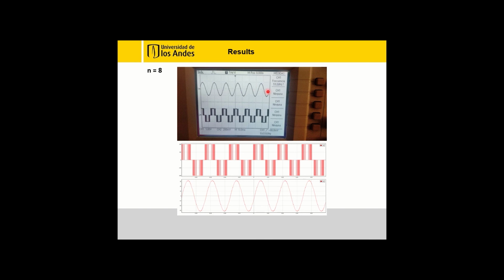for the inverter, where we have a DC to AC conversion. And the only problem with this is that when we start to increase the number of intermediate vectors, we had problems with losses due to the commutations. Besides obtaining an almost perfect sine wave, we were also able to obtain almost 60 hertz frequency for each case. And we were able to figure out the direct relationship between the execution rate and the number of intermediate vectors that we are able to define for the method.